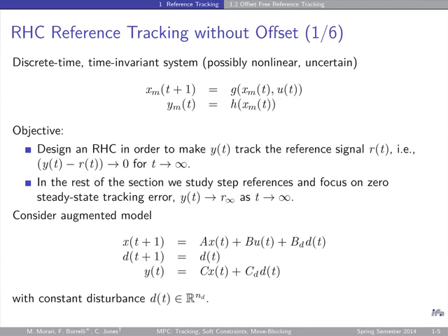If not, we'll continue. So this here at the top is exactly the bottom equation I had on the previous slide, which is the condition here. And so we derive from this the insight. I have an expression of what steady state x's and u's I need to get this output tracked perfectly. I will take those steady states and use them as targets now, just like I did before for my MPC controller. There's a slight correction here, I saw it just before: there should also be written target, comma, infinity.